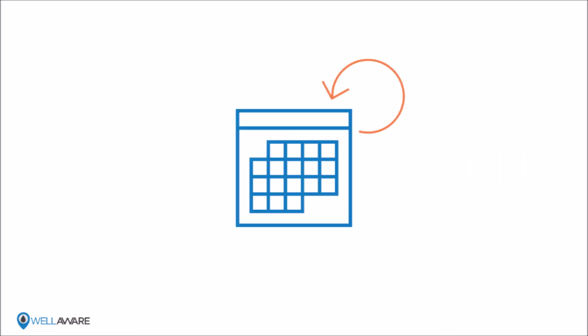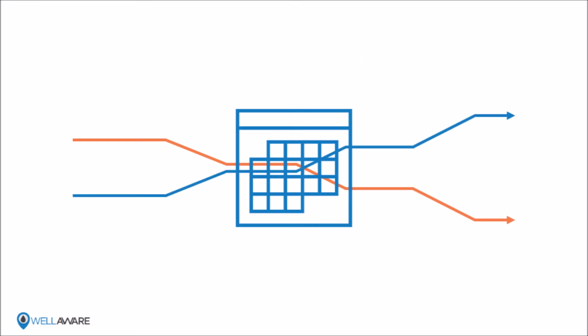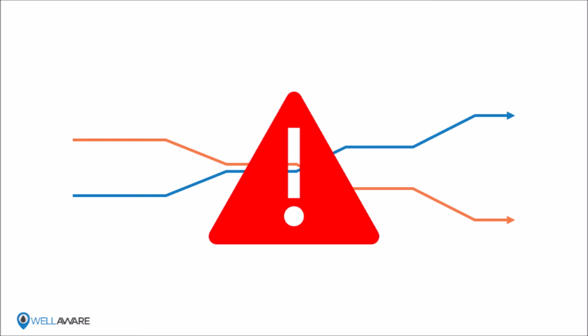Usually, pump set points are changed manually when a technician physically interacts with the pump to make updates. Let's say the technician makes the rounds once a month to get this done. The problem with this? Industrial processes are highly variable, and the rate at which this pipeline moves water might vary between 0 gallons per day and its max throughput depending on the processes which feed into the line. Because these industrial processes can change every second or faster, and chemical injection set points change only weekly, monthly, or worse, this introduces a lot of variance.